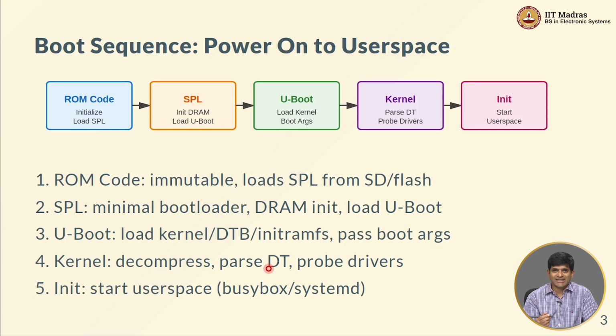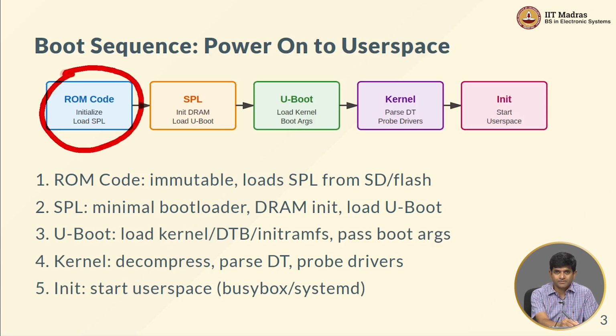So if I can basically initialize the program counter to a known value, and I then set up my digital hardware in such a way that at that address, in other words, if that address goes out onto the address bus, whatever is going to come back in response, because after all it's going to be performing a read operation, whatever comes back in response to that read operation should be valid instructions. How do I ensure that? I use something called ROM code.